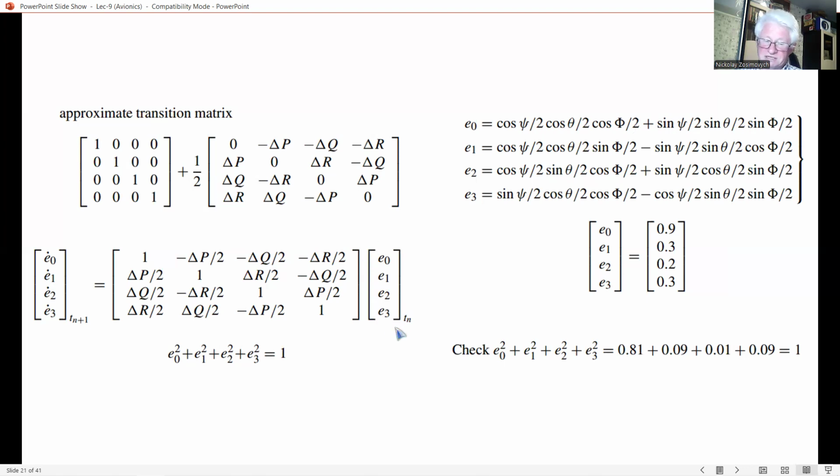The performance of the numerical integration algorithm can be further improved by using a second-order Runge-Kutta algorithm or a fourth-order Runge-Kutta algorithm, where very high accuracy is required, and by decreasing the integration time increment delta t with a more powerful computer.